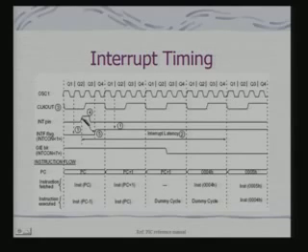So, here when the interrupt is occurring, what will happen? There would be a delay, and after that delay the INTF flag would be set. The flag is indicative of the source of the interrupt. And what is assumed here is your global interrupt enable flag is set. That means the processor is enabled to respond to your interrupt.